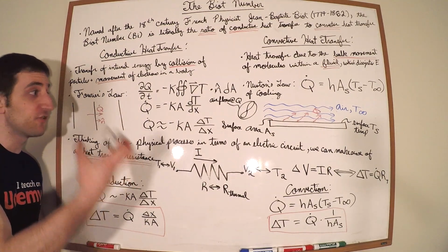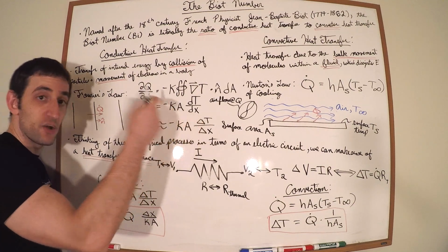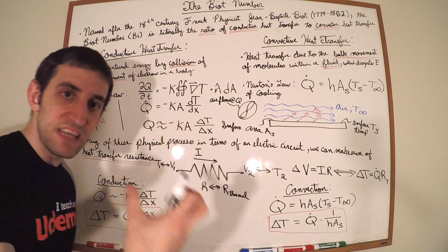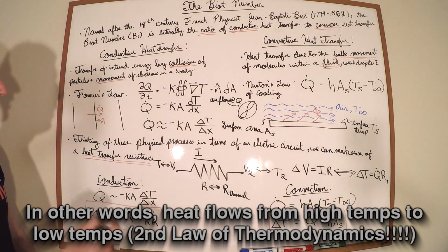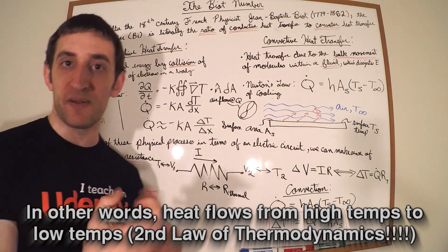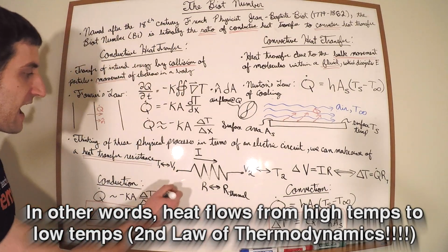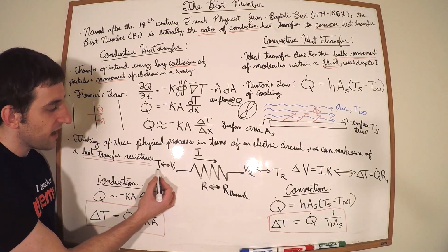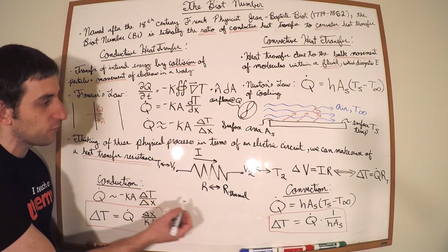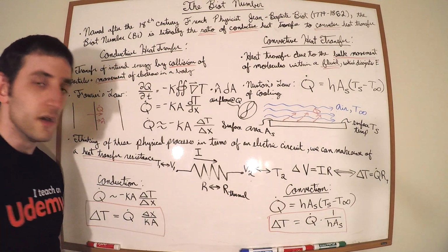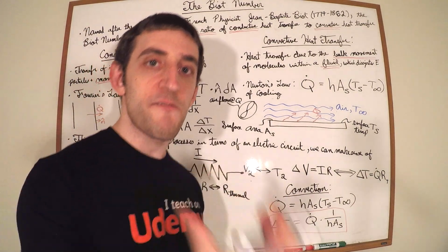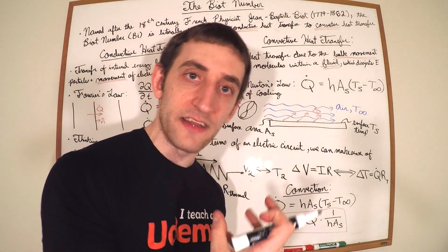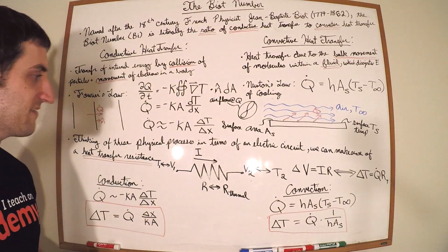It's the temperature difference. It's this gradient. The gradient drives the heat transfer, okay? So we can see an analogy between the potential in electric circuits and temperature in heat transfer, and that's why I made this analogy here between T1 and V1 and V2 and T2. They're analogous. They have the same philosophical idea inherent in those concepts.